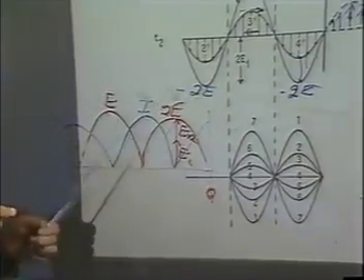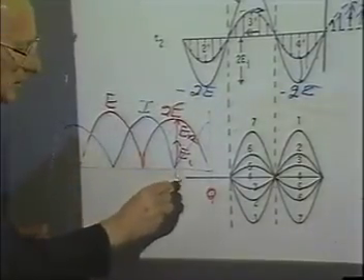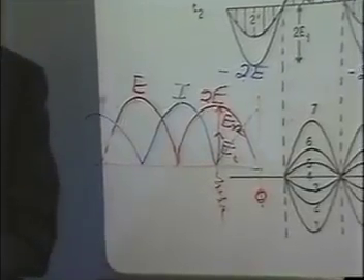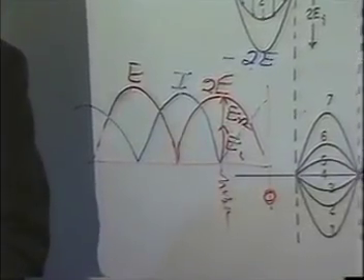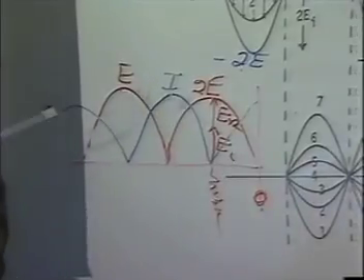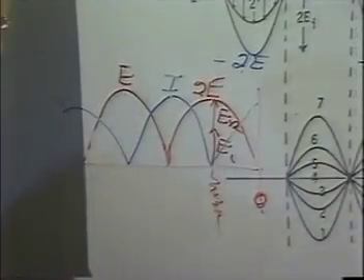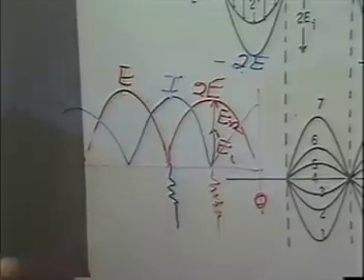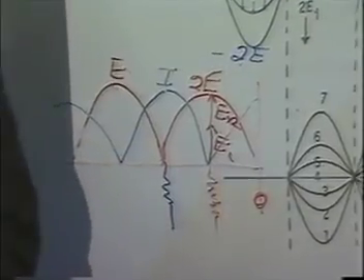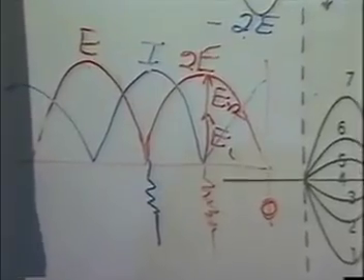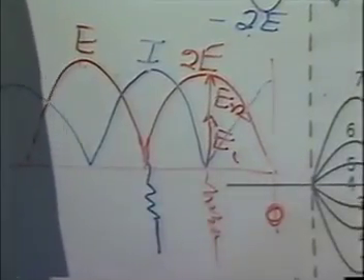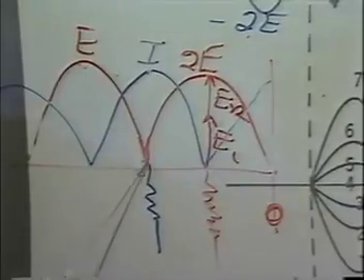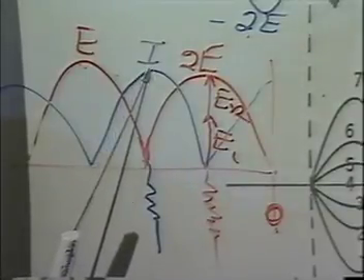If you looked at this from the standpoint of resistance, you know that this point has to be a pure resistance value because the two are in series, in phase, aren't they? Two signals are in phase. It has to be this situation here. What has to happen over here? This also has to be a pure resistance, doesn't it? In this case, it's zero resistance, but it's still a pure resistance of zero value. In other words, the voltage is minimum, the current is maximum.